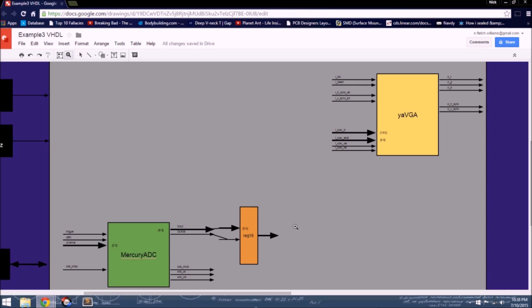If the ADC here drops below a certain value, then start capturing, which means write 0 into this address, then raise the write enable signal and record the data point. Then after a specific amount of time, increment the address to 1, write a new data point to that address, and keep write enable high. After we capture the entire screen to address 800, then we stop. When we stop, we want to wait for the next start bit.